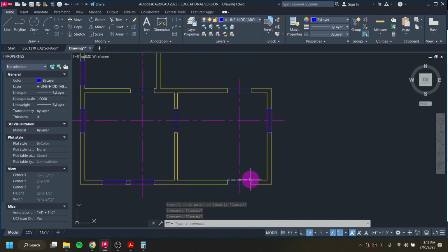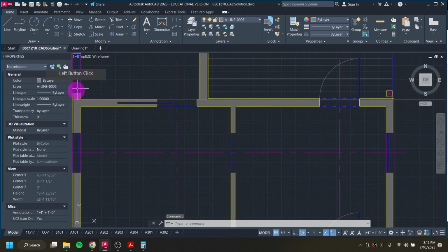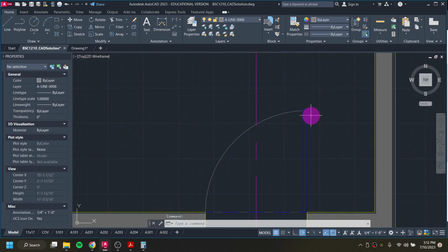Next, we can add in our doors, our regular swing doors and our pocket door. So we'll do our regular doors first. Now, doors themselves are going to be a typical amount. The thickness of this door is most likely going to be around 1.5 inches. Sometimes for some exterior doors, they might be 2. We'll just make ours 1.5 inches. The length of the door this way is important, because it needs to be 3 feet. If this is a 3-foot opening, the door itself has to be 3 foot long.